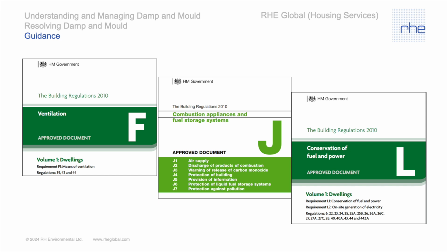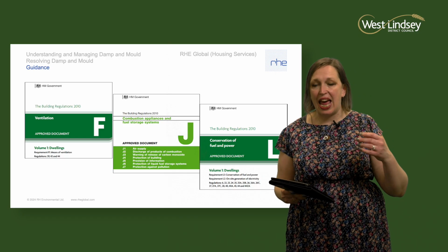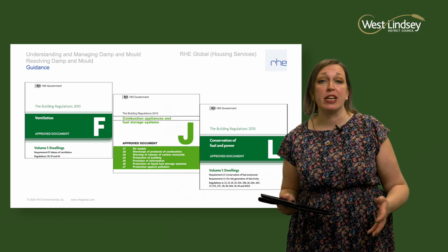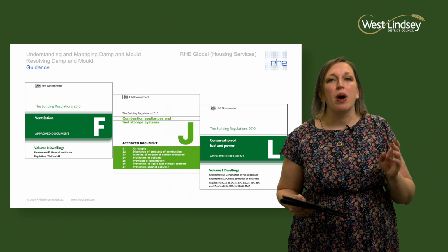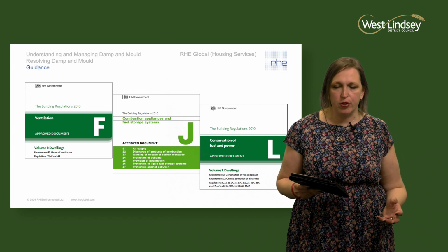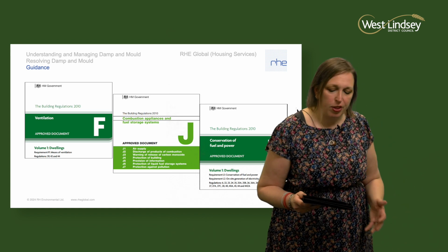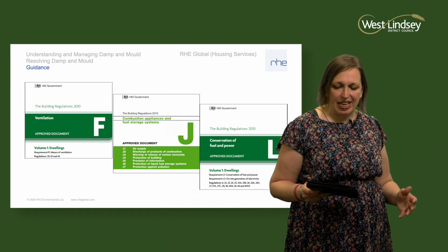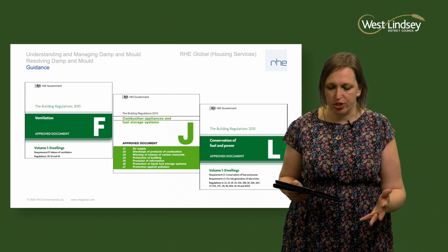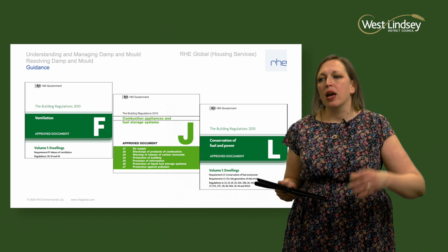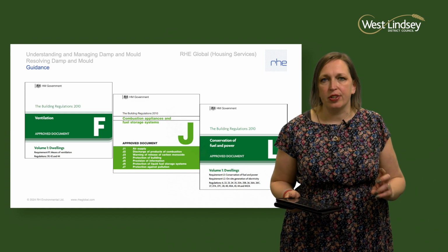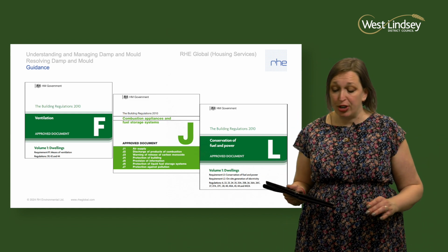And in terms of our building regulations, very similarly to what I said about the British Standard just there, when we look at parts F and L of the building regulations, there is also a different approach for traditional buildings, in that ventilation and energy efficiency improvements should only be made to vapour permeable construction where it won't cause deterioration of the fabric of the dwelling. So really important to recognise, though, that that doesn't mean don't do anything. What it means is that the measures should be appropriate to the dwelling, and it might mean that they don't meet the ideal prescribed standards, but we still need to make as much improvement as we can.